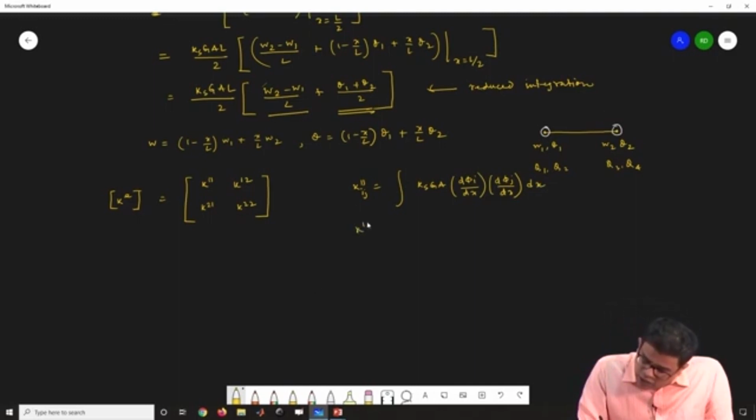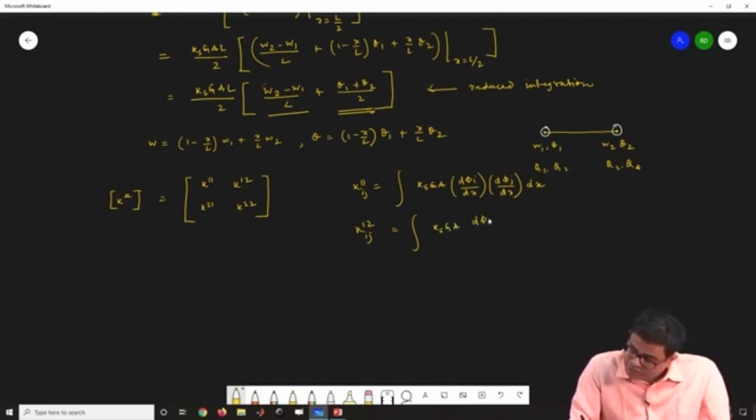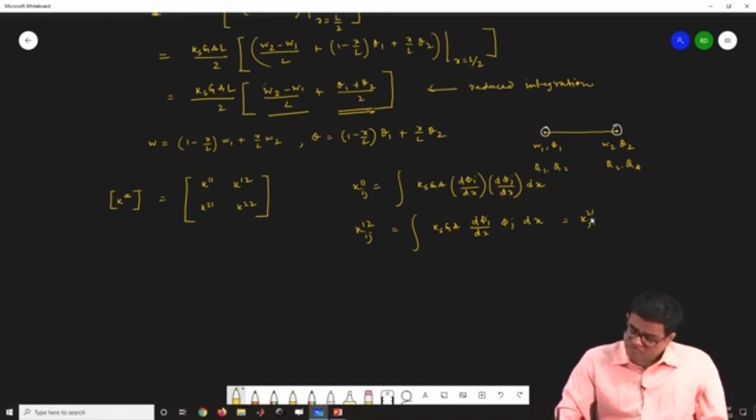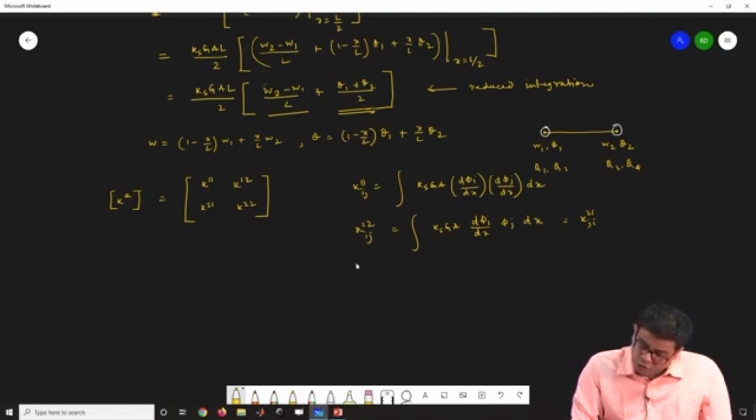Now K12 ij is again Ks G A, d phi i dx times phi j. So this is actually K21 ji. Also we know this. Now this is K22 ij, it will have two terms.